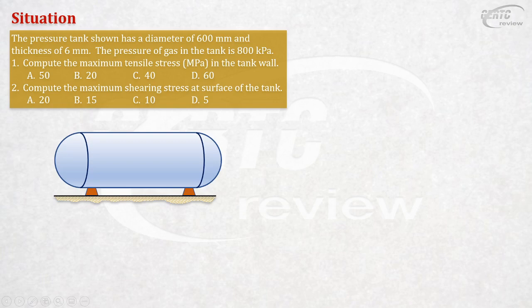So, kung thin-walled cylinder, it should not matter if you will use the inner or the outer. But, well, of course, by principle, it should be the inside diameter. But it should not matter na malaki yung diferensya pag ginamit mo yung outer or the average for that case. It should not. Because if it will matter big, then that is not a thin-walled pressure vessel anymore. That is a thick-walled. That's my answer to that. Okay. Sige. So let's start.